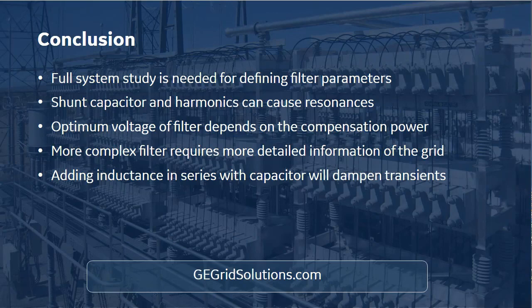Okay, and there's one question: is your product scalable? As our projects vary from a few megawatts up to 100 megawatts of renewables. Also a good question, and all capacitor banks are scalable. These capacitor units are like building blocks. So if the power increases, we just increase the number of capacitor units in there. We connect more of them in parallel to obtain more compensation power.